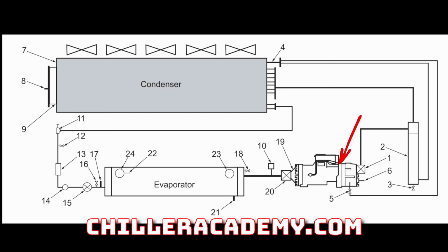So a York YCIV, for example, their minimum speeds, I think, are 50 or 60 hertz, but those are 200 hertz motors, give or take. There's a little bit of fluctuation there. But for the most part, those ramp up to right at about 200 hertz at the top end, and that's their full speed. And that's what they're designed for, even though the overall chiller is still a 60 hertz chiller.